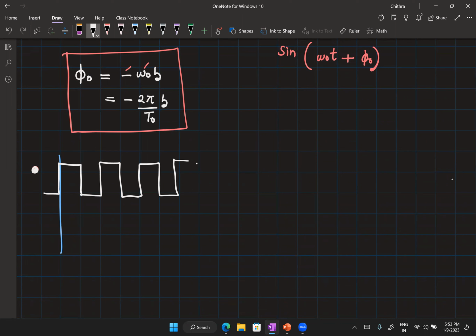Right now, if this is going from -1 to +1, and if this has a frequency given by omega naught, then I can write my in of t as a collection of sine waves based on Fourier series. So this is going to be sinusoids which are harmonics of omega naught t. And for a square wave going from -1 to +1, the Fourier coefficients will be 4 by n pi. And given the symmetry of this signal, we have to sum it up for odd n, right?